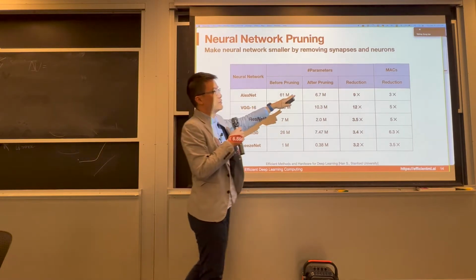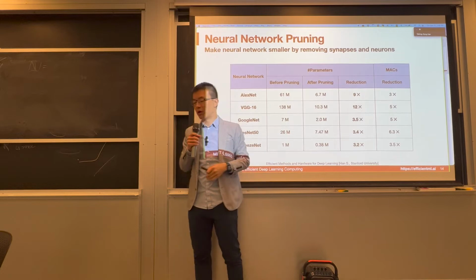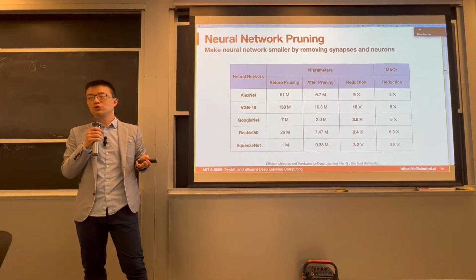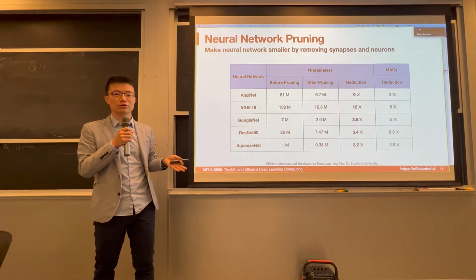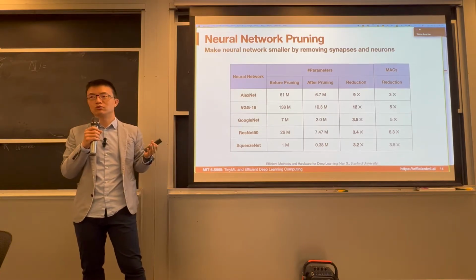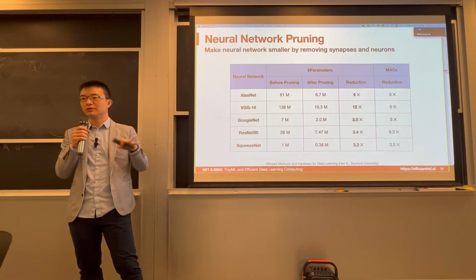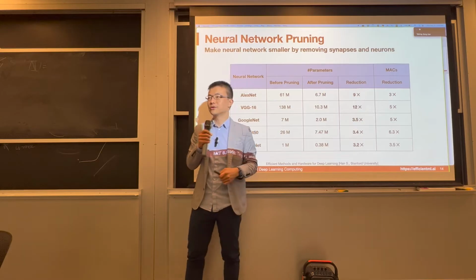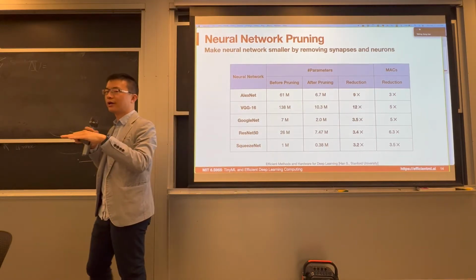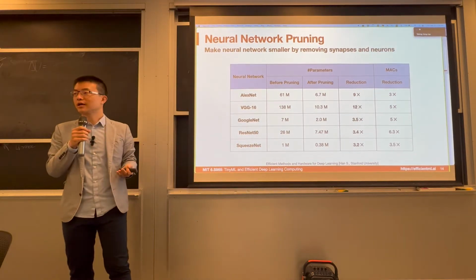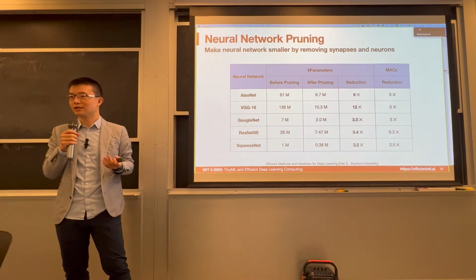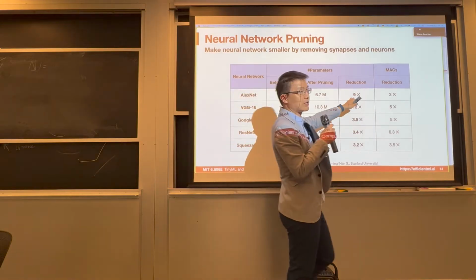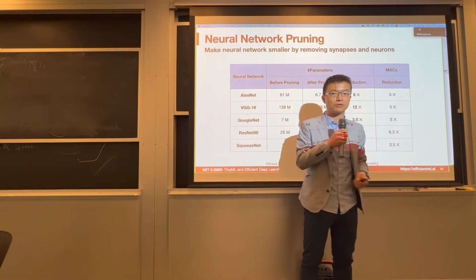And for the MACs, that is the multiplication of 7 terms. How many pixels you have to calculate? That is output resolution height times output resolution width times the channel of the output. And how many arithmetic operations we have to do per pixel? That is kernel x, kernel y times the input channel. So altogether, you have to multiply 7 terms together, right? So they have different calculations. Therefore, the reduction of the number of weights is different from the reduction of the number of MACs.